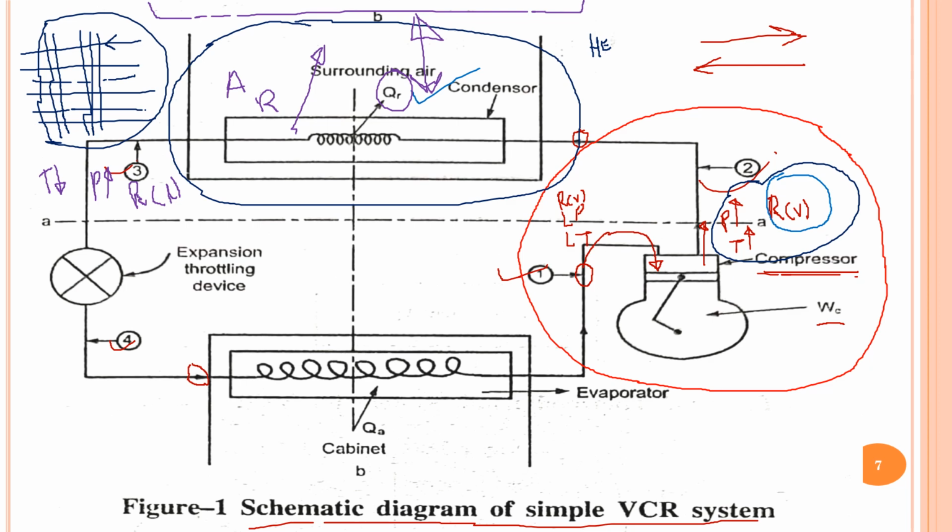So you can see here high pressure, high temperature vapor refrigerant is converted into low temperature, high pressure refrigerant in liquid form. So at end of condenser, when the refrigerant is coming out, the state is low temperature, high pressure refrigerant in liquid form. All this thing what I am discussing is explained in the next slides.